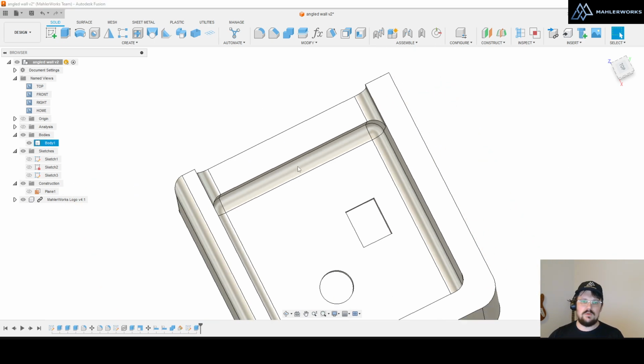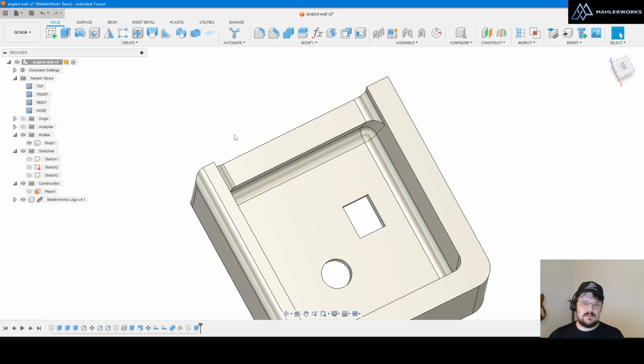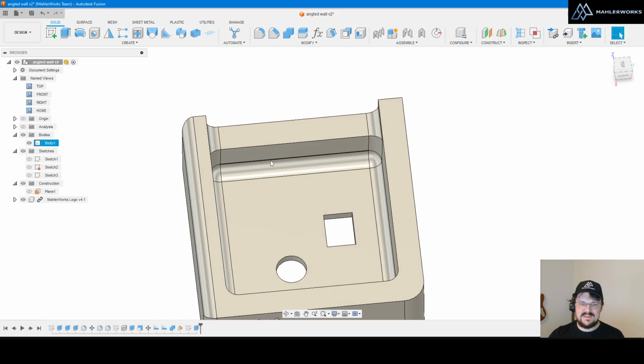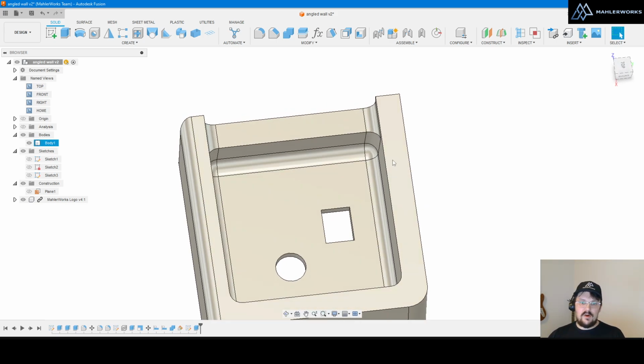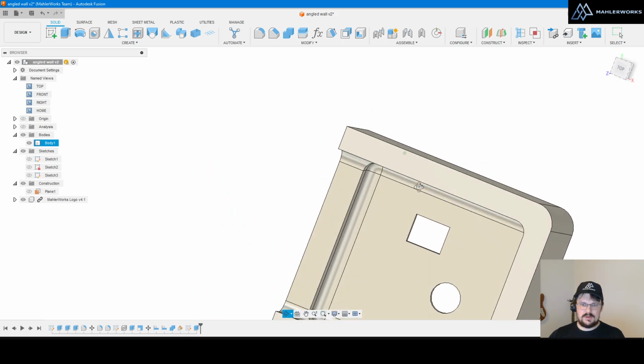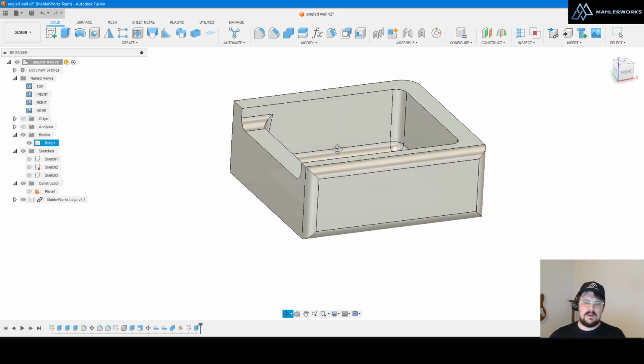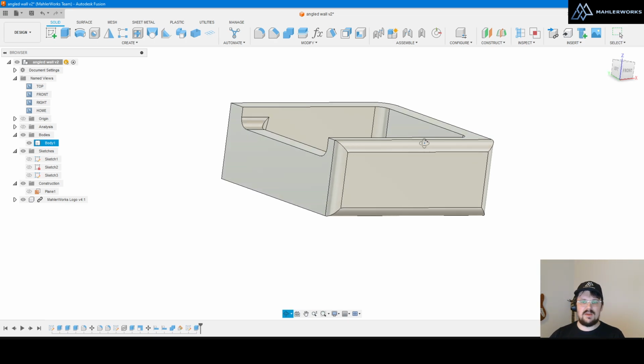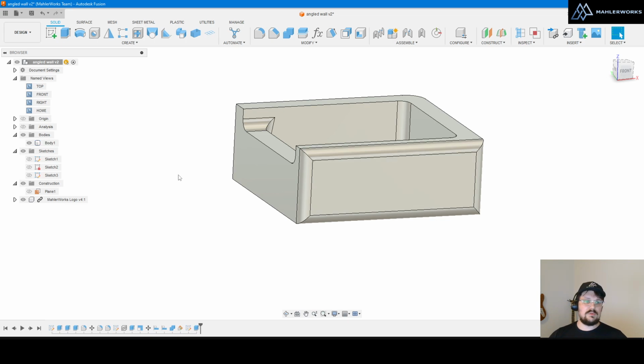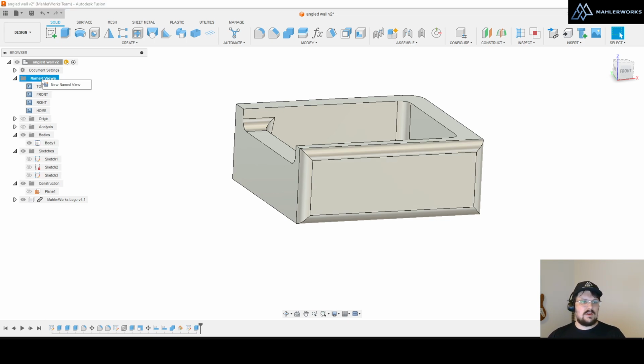So I want to look down this angle. And so what I'm going to do is make a named view once I'm oriented looking down this wall. For now, it might be a little bit tricky to look properly down that wall, but we'll get there in a second. I don't want to jump to another tip yet. But let's say this was a view that I really wanted. What I can do is right-click on Named Views, say New Named View, and ideally, I'm going to rename that view to, I don't know, I was going to say random.